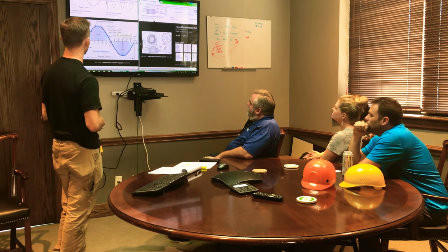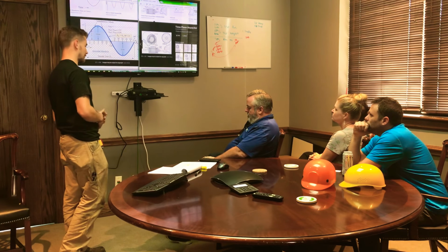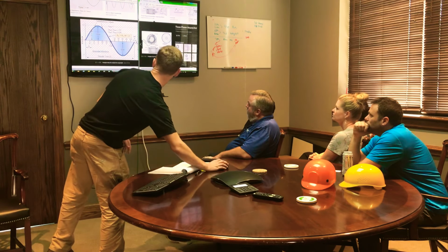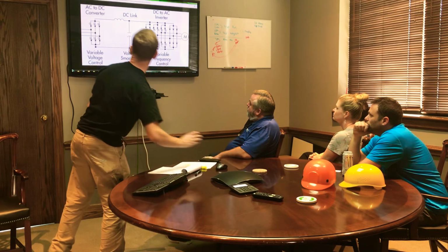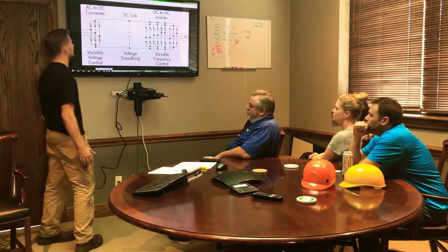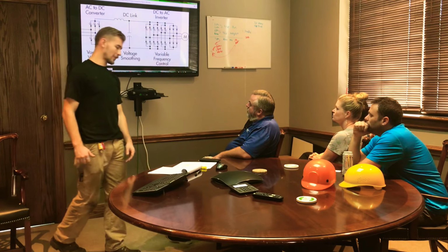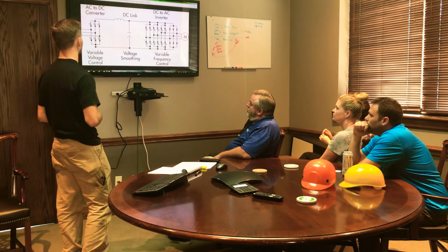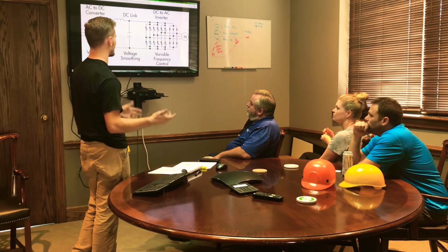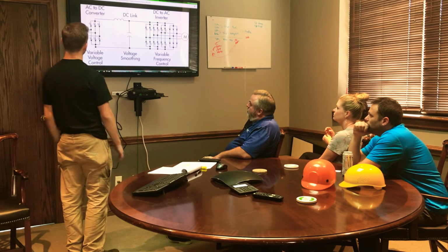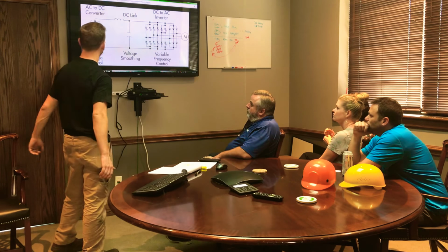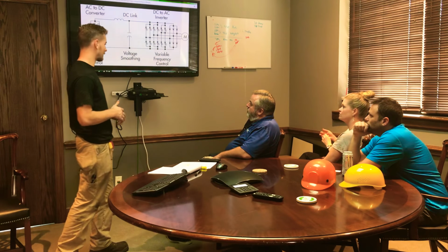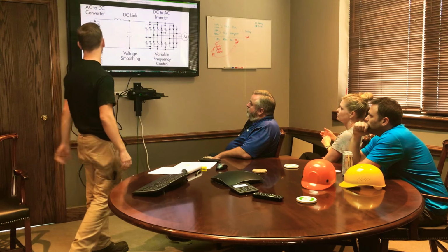Now we can move into the specifics of what it does with the electricity in order to enable itself to do that. So the first step in this process is the AC to DC converter. Many people don't know this, but the VFD works all of its magic in DC power and then outputs AC power. So it converts the alternating current to direct current by use of diodes, which are basically check valves, if you could correlate it to plumbing. It allows the current to only flow in one direction.